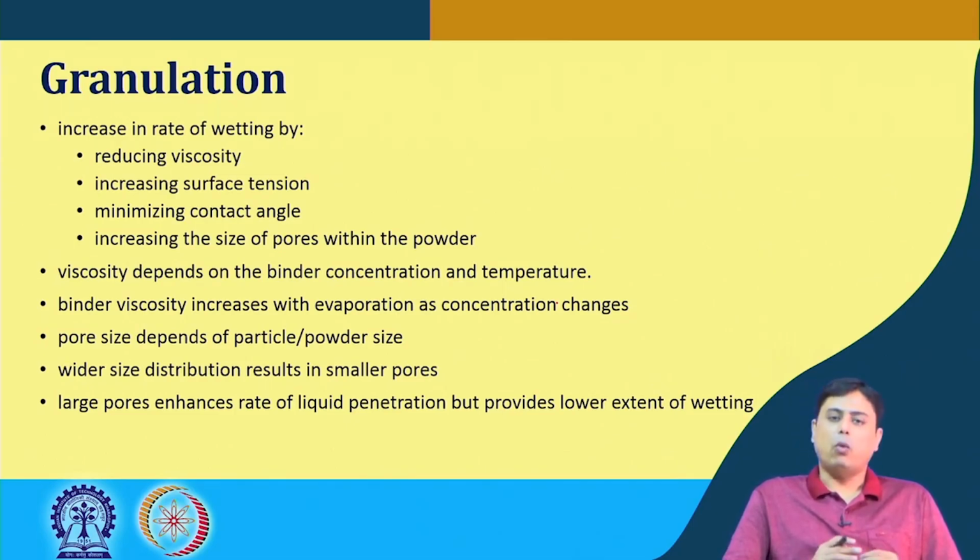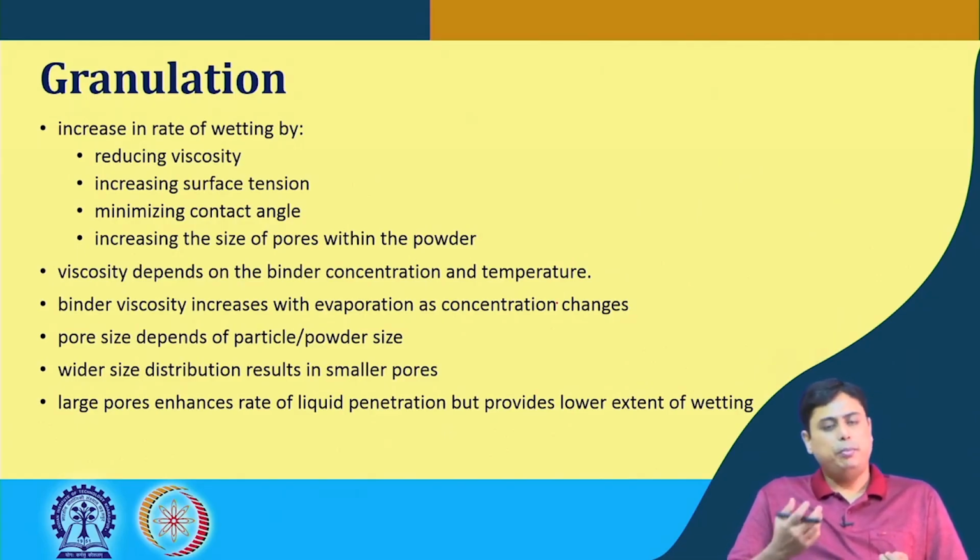If we have wider size distribution of the particles, we can find smaller pores. Now, bigger particles will provide us bigger pores, smaller particles will be more compact during the packing, so they will provide us smaller pores. Now, these larger pores definitely enhance the rate of liquid penetration, but provide a lower extent of wetting.